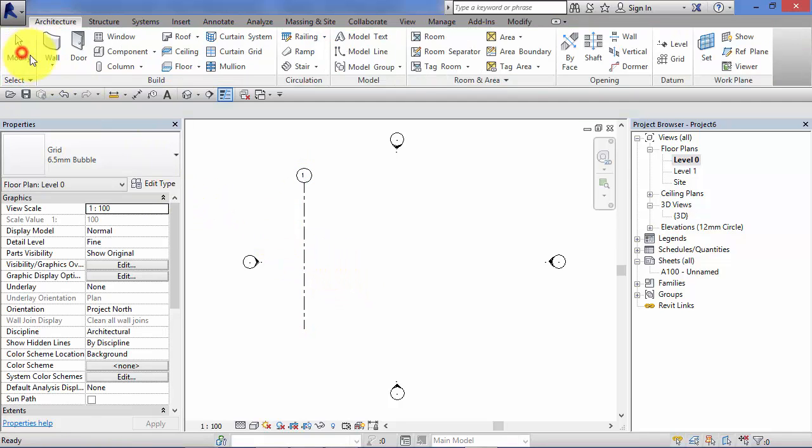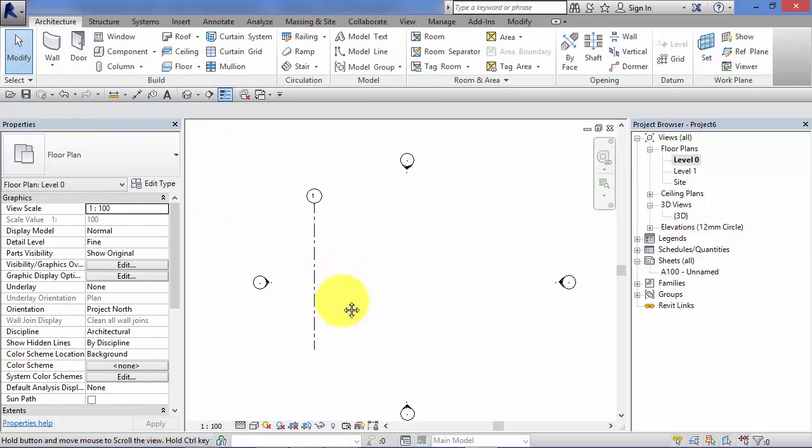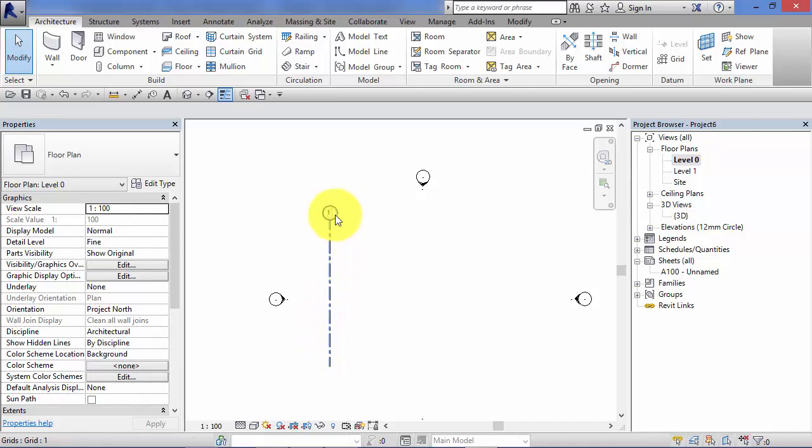Let's just take a quick look at what Revit has produced. So here is our grid line. This is the 2D graphical representation of it. It's got a bubble or a grid head by default at one end, and it's got a reference. So by default Revit's going to name or number the first grid line number 1. You can change that to whatever you need, and Revit will follow the sequence that you set it to, and I'll show you that later on in the unit.